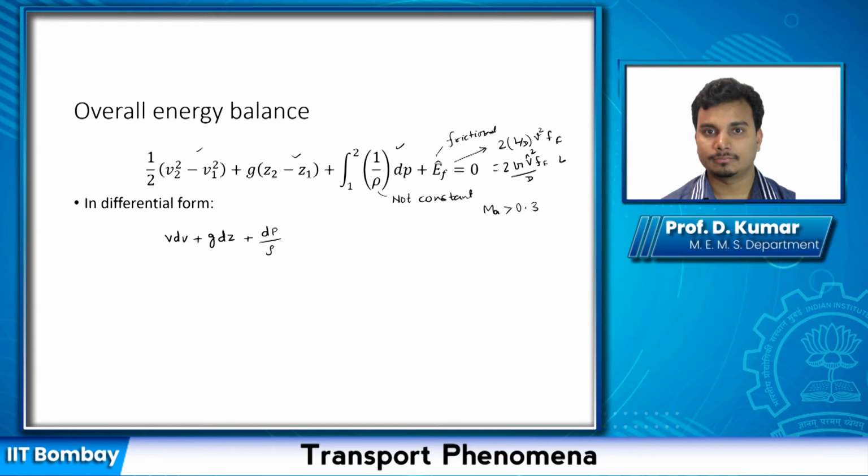So here the assumption is that the friction factor is independent of velocity, which is true, because at very high Reynolds number the curve is flat, horizontally flat, so it doesn't change much with Reynolds number. So it's independent of Reynolds number. It does depend on surface roughness, however.